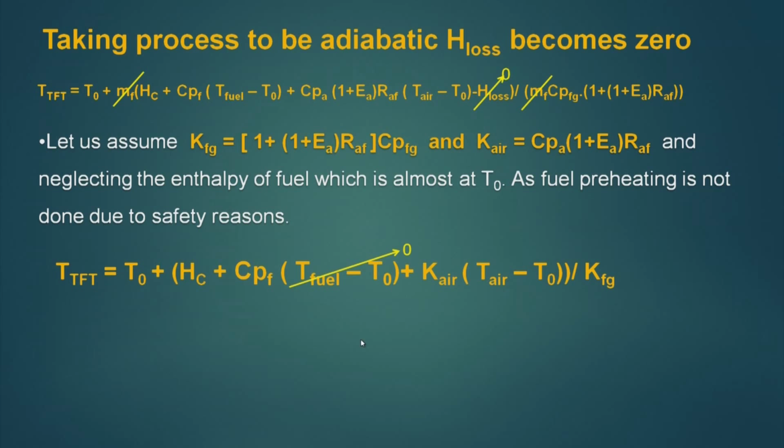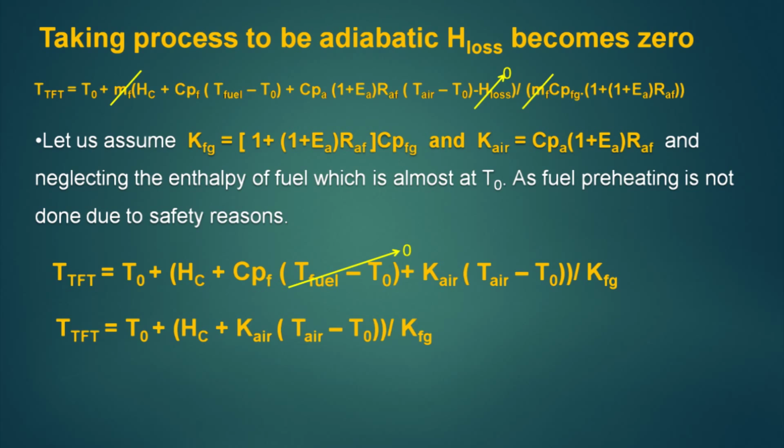Now, if I consider there is no fuel preheating, in general fuels are not preheated for safety reasons, then T fuel will be equal to T0, that is, the ambient or reference temperature, and hence T fuel minus T0 will tend to 0, and TFT, which is the theoretical flame temperature, will be equal to this.